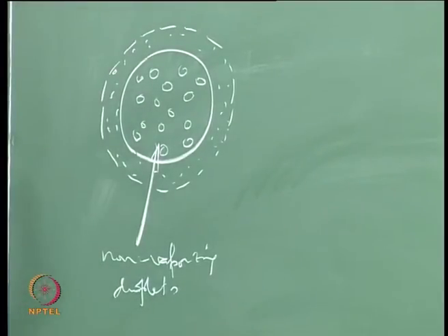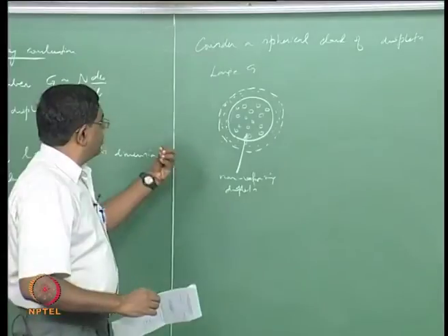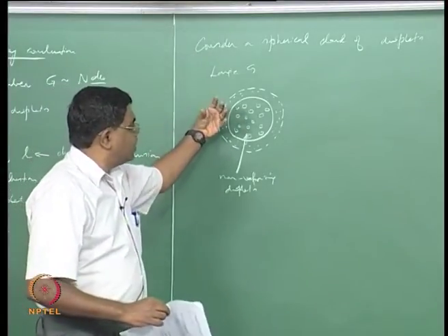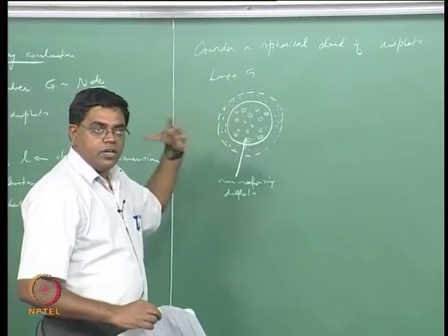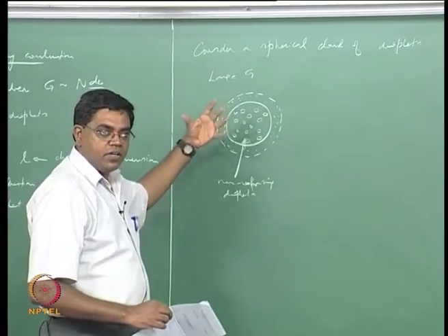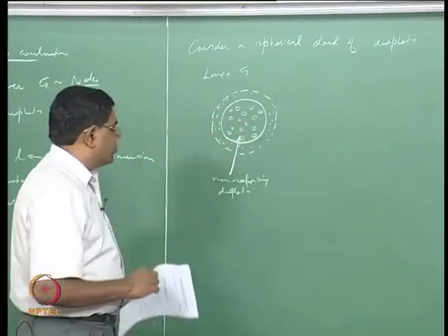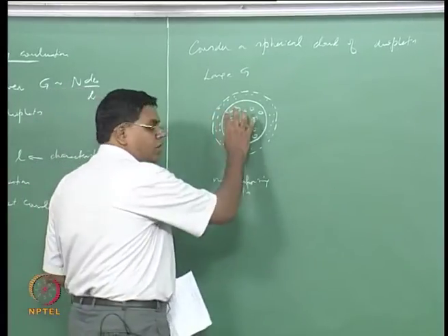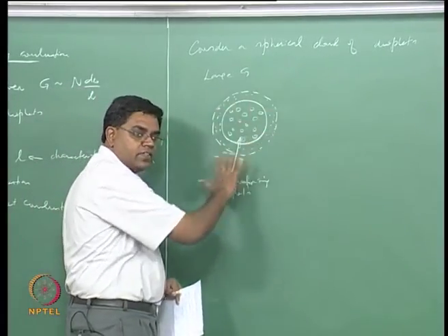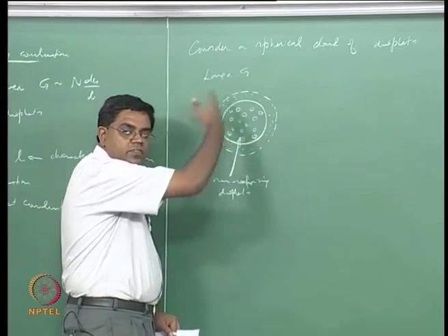There is another way of thinking about this. You can look at a spray that is coming out of the burner in a cylindrical manner. It does not have to be spherical, but you can look at things happening in a circular manner as a cross section. So you have a non-evaporating core and an evaporating surrounding that forms the spray.